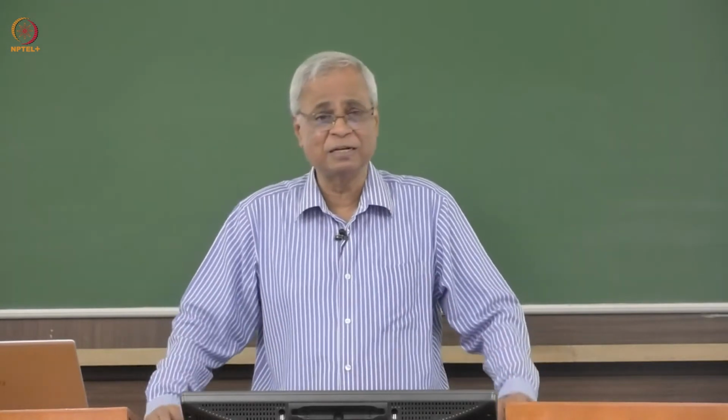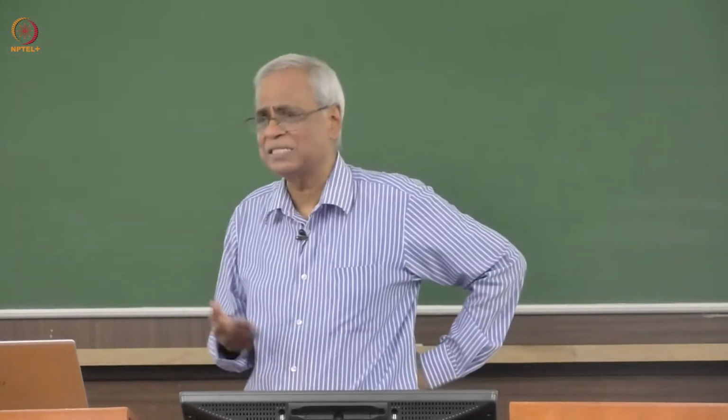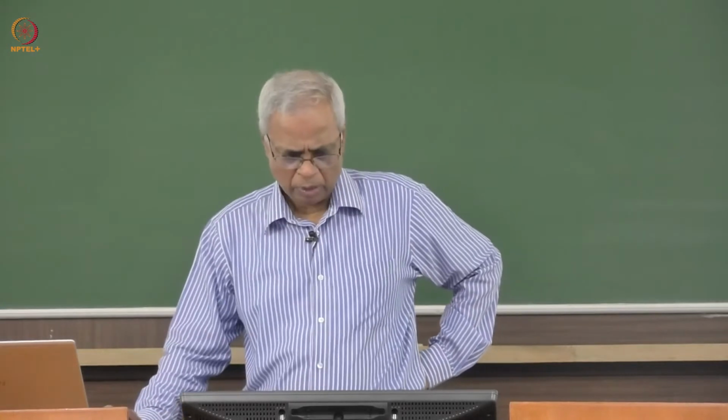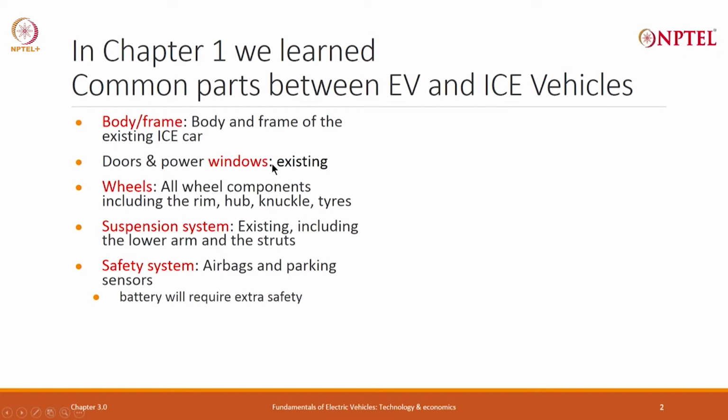Can you change the material used for body? Well, that is just something that work has just started and it is a future thing. Similarly, doors and power windows pretty much existing. Of course, you will probably not have manual, you will have all with motors and which requires electricity, which a separate battery was used in a petrol vehicle. Today, you do not need that separate vehicle battery. You will take the existing battery, convert it to the right voltage and drive all these motors for windows and doors and things like that.